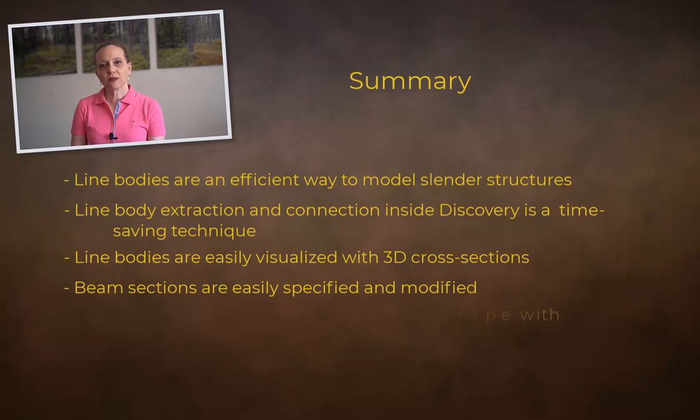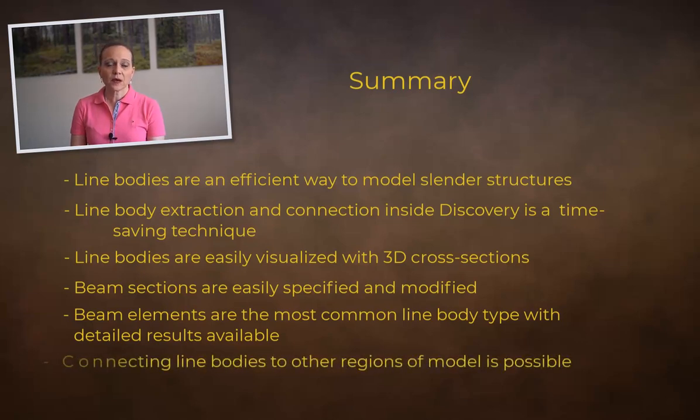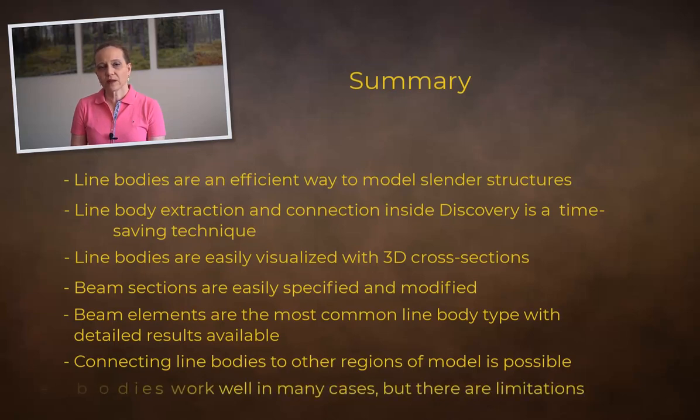We discussed that beam elements are the most common line body type, with detailed results available from the forces and moments to more detailed stresses and strains. Connecting the line bodies to other regions of the model is possible, and we showed some simple examples. Finally, while line bodies work very well in many cases, understanding their limitations is important for proper usage.